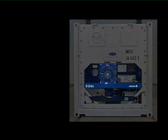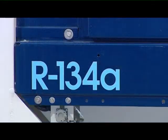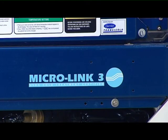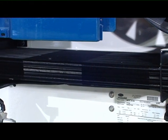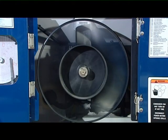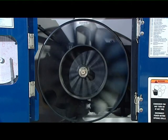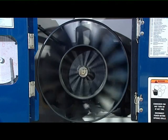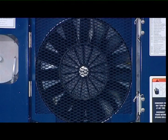Condenser section. The condenser section includes air-cooled condenser coil, condenser fan grill, condenser fan, condenser motor. The condenser fan causes air to be drawn from the bottom of the condenser coil and to be discharged through the condenser fan grill.